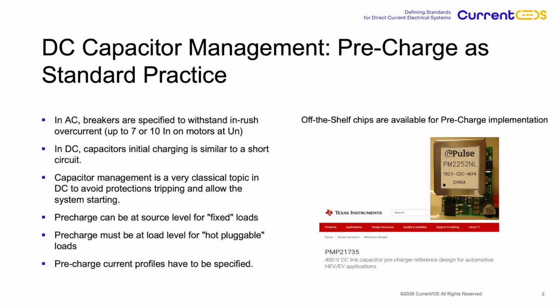This concept might seem exotic to those accustomed to alternating current systems, but pre-charging is a standard practice in DC systems. For example, all electric vehicles with DC chargers already have built-in pre-charging systems. Companies like Texas Instruments have even developed dedicated chips to control pre-charging. Managing the pre-charge of capacitors in DC systems is a well-established process for ensuring smooth operation in DC installations.